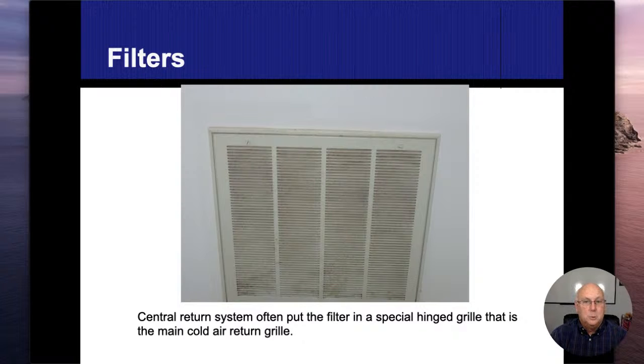One of the measurements I'm hoping you're going to be taking in your system is what we call the delta T, or the temperature change going across the heat exchanger. So it's what they refer to as the temperature rise. We'll find that number on the data plates inside the furnaces. Typically, they're going to be a 30-degree range, all right?